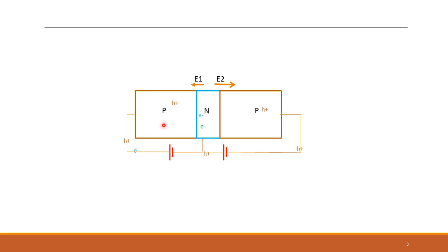Third, we have this PN junction, and we're going to have the minority carrier in the p-type diffusing, and we saw that in the diode, and that is an electron current which is going this way. You can see that here, because the minority carrier in the p-type is the electron, which then diffuses here, and that has to be supplied from the majority side. So it is injected from this side to this p-type, diffusing here and then going across like this. The electron current, we know, goes opposite to the flow of electrons. So that also goes this way, in the direction of the hole current.